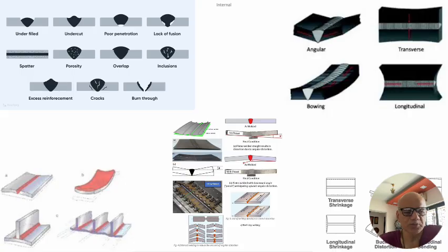But porosity is a small defect, whereas here it is a large defect which creates a planar defect. It is not a volume defect, it is a planar defect, a crack, and those are very, very difficult to take up under the load. The cross-sectional area in that particular plane drastically reduces, and the weld cracks or the entire equipment has a failure.